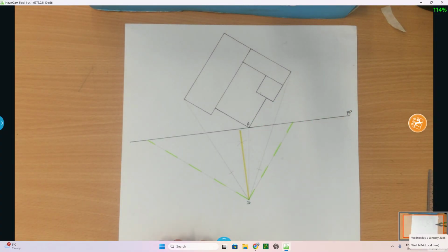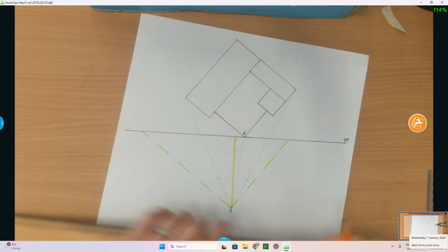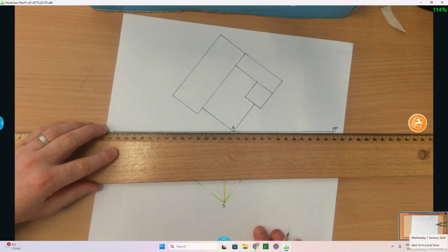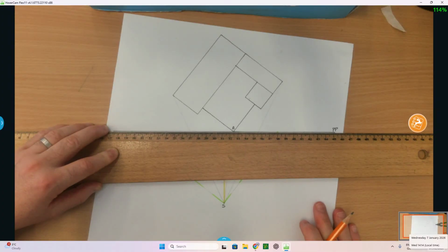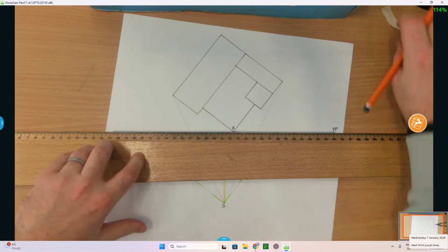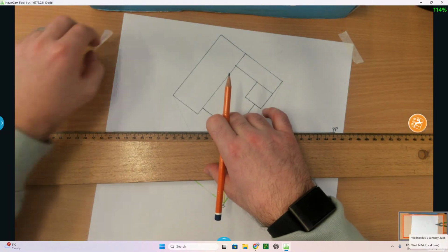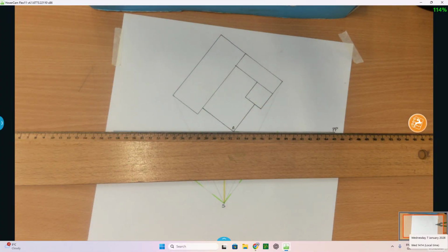Just going to take off the tape. I'm going to rotate my sheet just slightly so that my T-square will now go in line with it. And what this does is it eliminates the fact of using sliding set squares. So rotate the sheet. There we go. Take this guy. Get my masking tape. I'll tape down here. Okay. Now the next rule is go back to the sheet.